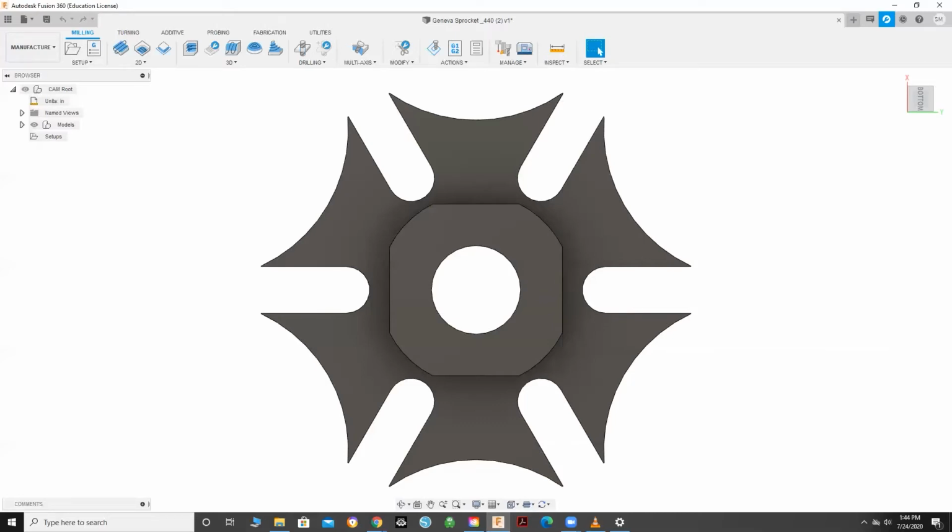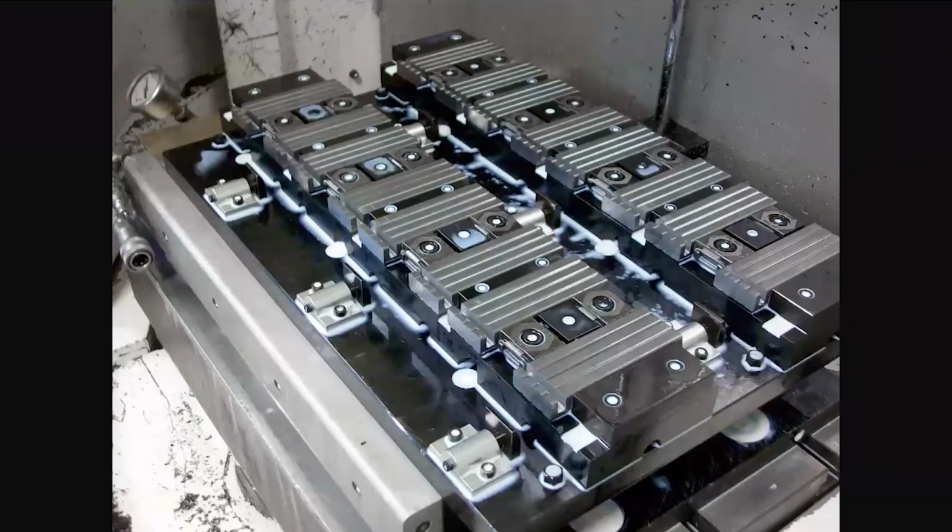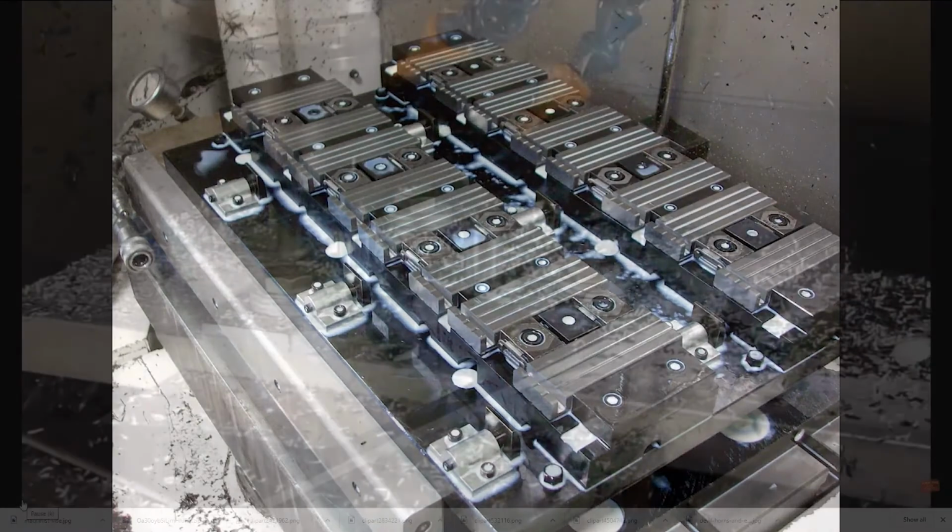In the machining world, fixturing is one of the most important skills to learn. How you fix your material can speed up or slow down the entire process. You can have fixtures that can make multiple parts at once to speed up the manufacturing process. Here is a picture of a fixture that holds 16 parts at once. With production like this, the fixture is generally included in the model to avoid tool collision.